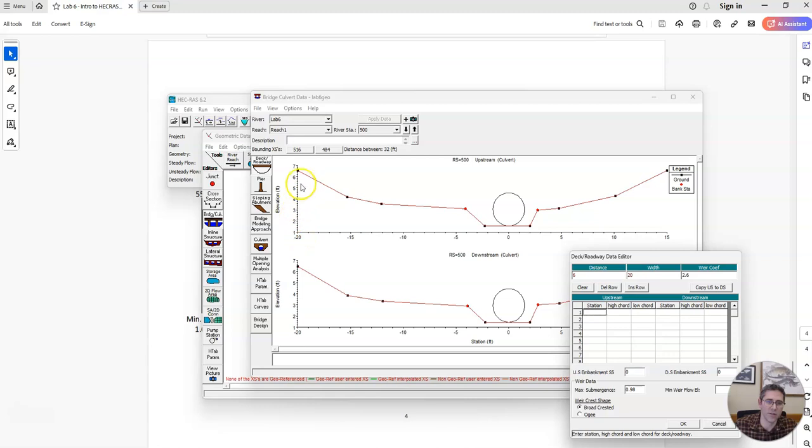So you can see here, if I enter -20 at 6 foot, it's going to start on the left side of this line, which is good. I could also enter -50. That's fine. It doesn't really matter as long as I'm to the left of this line. So upstream, I want -50, and I want downstream -50 as well. Also, on this side now, the x-coordinate, the station, I'm going to do the same thing. I'm going to just put 50 and 50. Alright, so it's going to draw this line across, but the high chord is the elevation of my bridge, which is 6 feet.